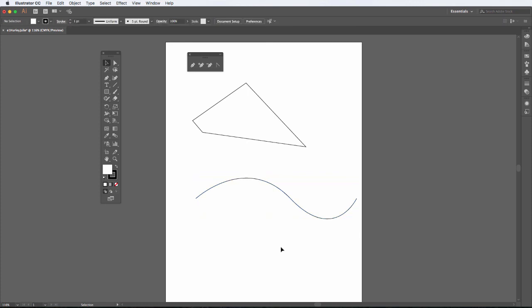Okay, going back to our pen tool, go ahead and click P on your keyboard or click the tool here. This showed you a nice smooth curve. Now I'm going to show you a smooth and a straight line. So we can do a smooth curve, and go back and click on the anchor point to make it straight.